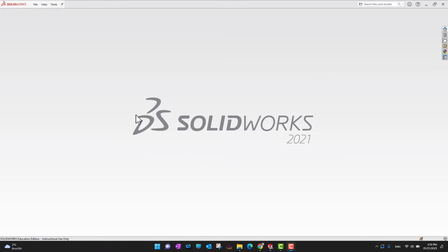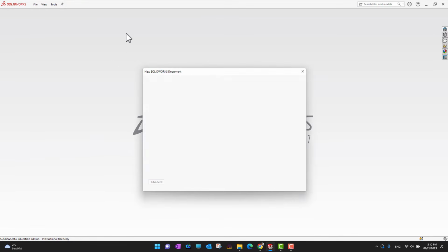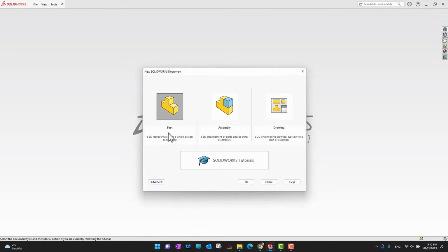I'm going to go into SolidWorks and let's start with a new SolidWorks part. If you want to start from the part, you can click on New, and here, if you want to start with the part, assembly or drawing, you can just select. As in this video we are going to design our first part, I'm going to select the part and then press OK.